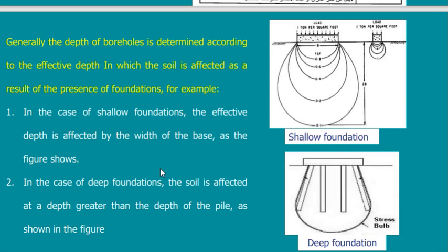No, it will just affect a few meters. How much? Scientists studied this by experiment and found that it is down to twice the width, the breadth, of the foundation.